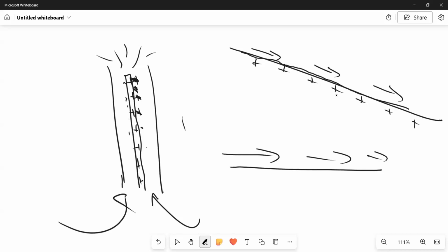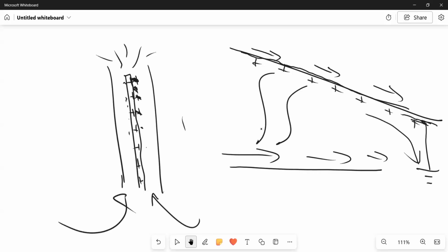And over time, they'll put a metal coating somewhere on this chute and ground that metal coating, so that these charges are, from time to time, going to flow down to earth. So no way can we have a spark going down to the ground, and maybe if you have something flammable, cause a fire. So grounding is very important.